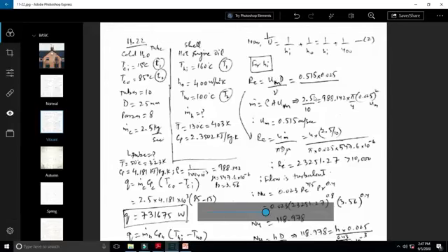And the Nusselt number would be calculated with the help of one of the expressions. So the same methodology will now be applied over here. In order to select the appropriate expression of Nusselt number, we need to know whether the flow is laminar or turbulent. So we will first find out the Reynolds number.